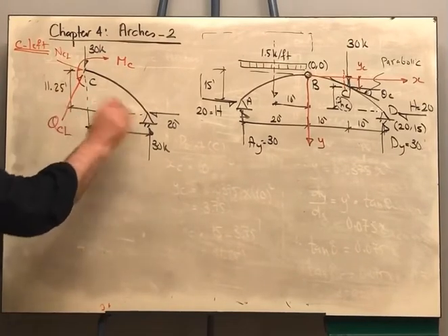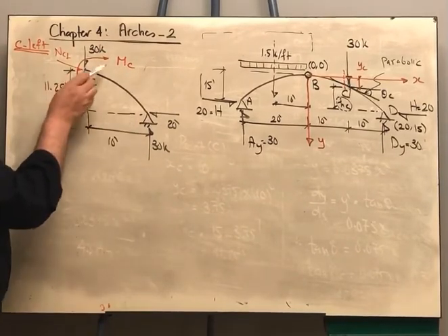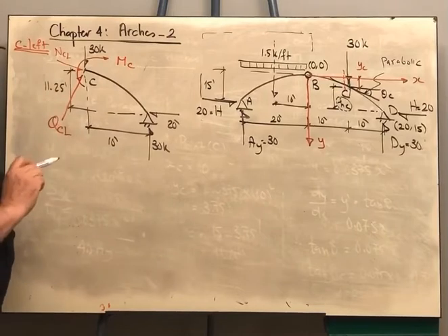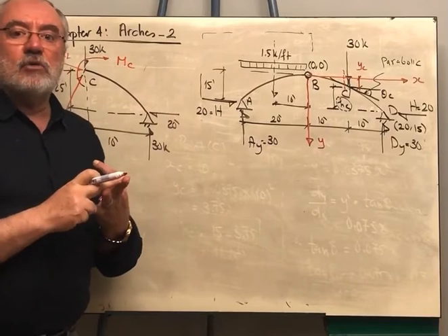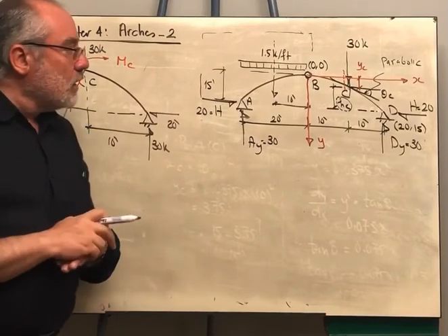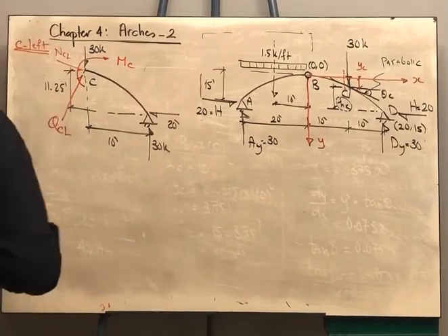Now I need to solve this. Now at the cut section we indicated all of the internal forces. We can apply sigma Fx, sigma Fy, and sigma the moment about any point to determine the three unknown internal forces we have.